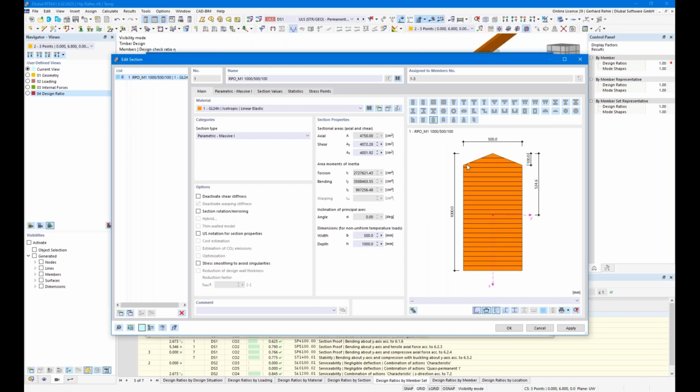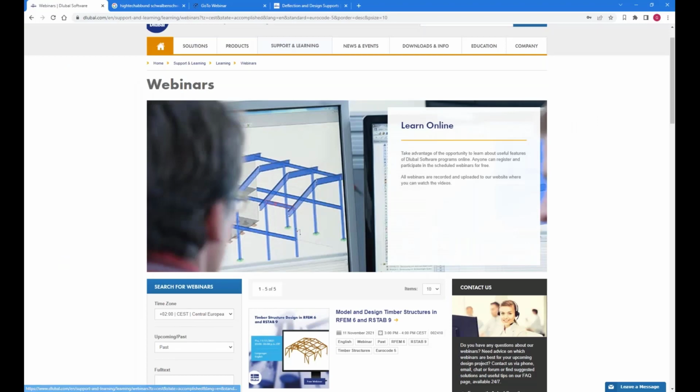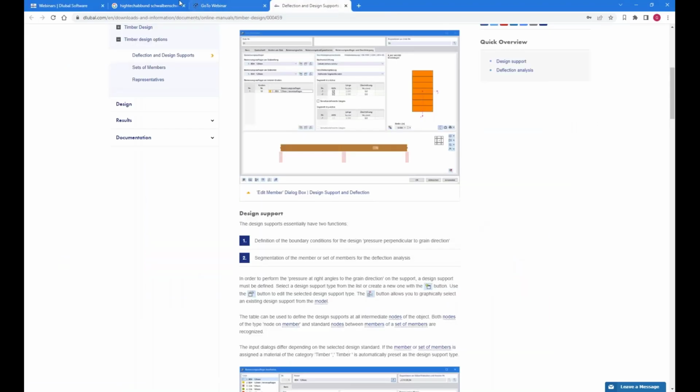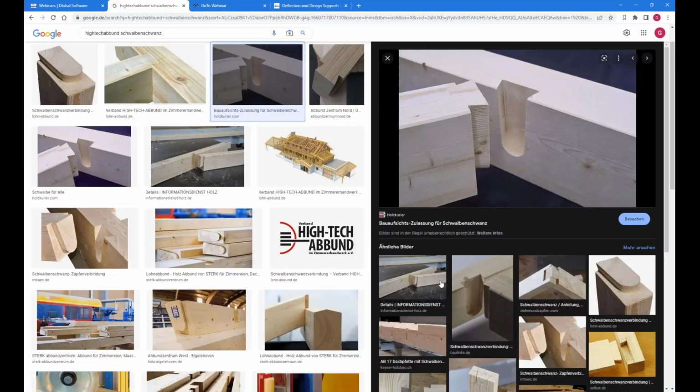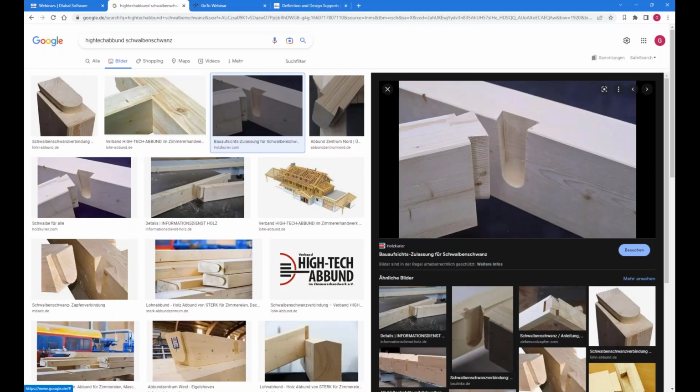But when we think about connections, so when we think about how to connect the beams to the hip rafter, where I live, it's really typical to use these dovetail connectors, for example, because you don't need additional fasteners. Of course, you will apply fully threaded screws. That's clear for uplifting forces, but that's an easier way. But of course, you will create an additional notch here. So another cross-section reduction, which needs to be considered.